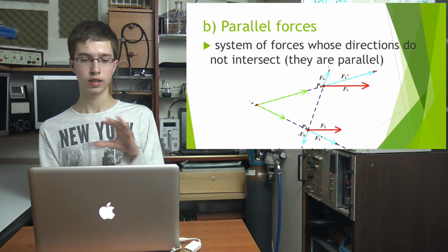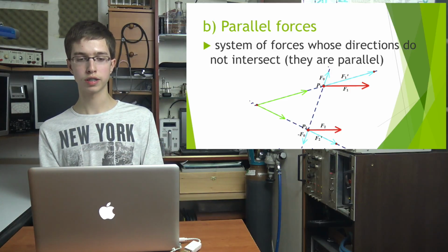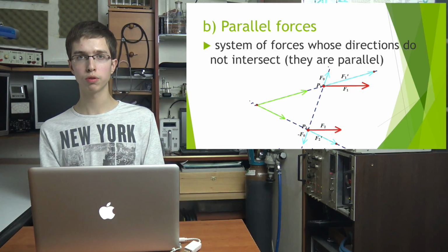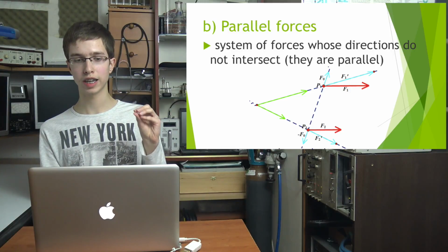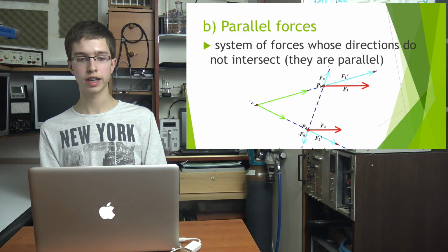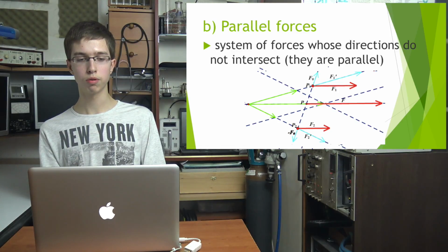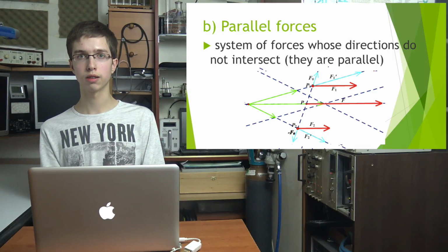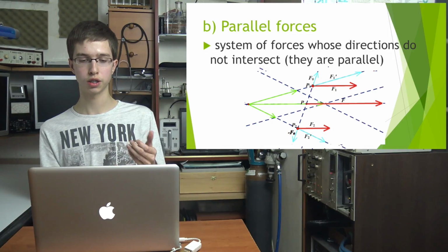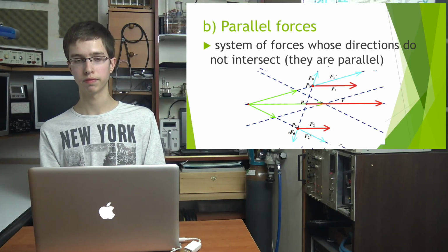Now we translate these two forces F1 apostrophe and F2 apostrophe so as to have the same tails in their directions' intersection. Now we sum them up by the parallelogram method, for example, and now we translate that resultant force so as to have the tail at the line segment connecting P1 and P2. And here is P, which is the point of application for the resultant force F.